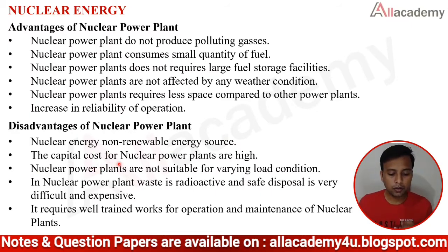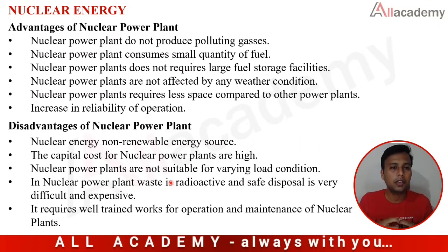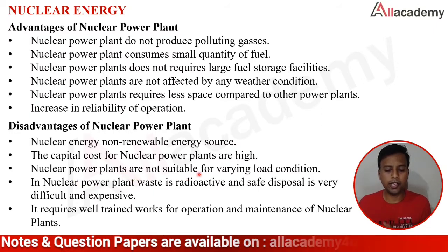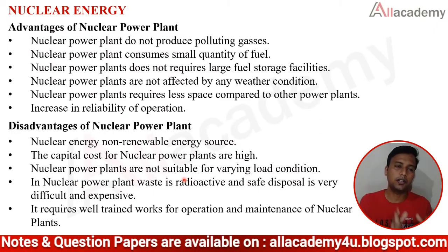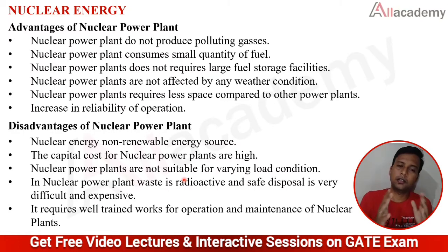The capital cost of a nuclear power plant is high. Obviously, we need to construct a strong reactor vessel and strong construction, because whatever nuclear radiation or nuclear energy is there should not come out from this reactor. So it requires a heavy investment. The nuclear power plants are not suitable for varying load conditions. Whatever fixed capacity we construct these plants for, they will be running under the same capacity.